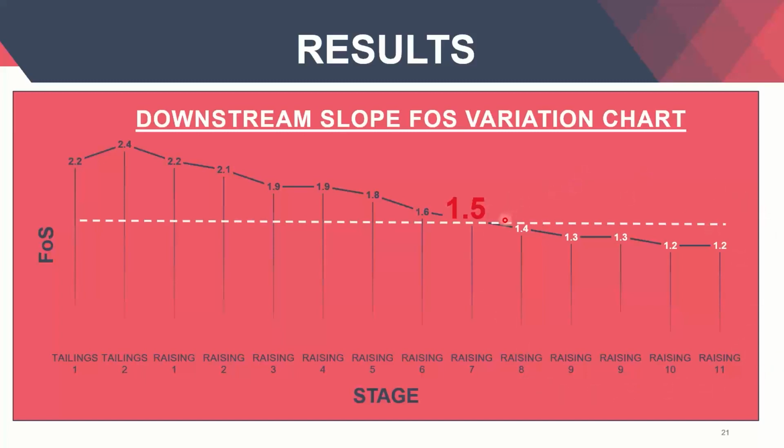So which means that we need more support systems. But again, if we go back a few minutes, I had clearly mentioned that this was a pre-feasibility report. That is why we needed to check what exactly we are looking for. So we understand the amount of rockfill we have put in there is not enough, and after the seventh raising, the factor of safety will go down. So in the second part of this webinar series, that will come probably a month or two from now, we will show you the more comprehensive design of what we exactly did for this model or for this project.